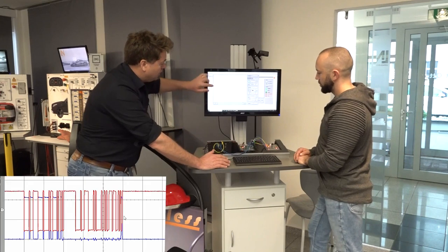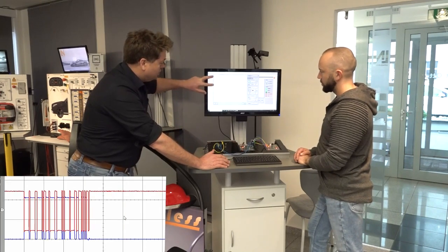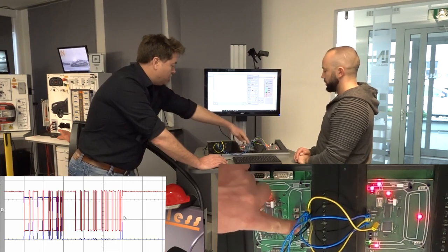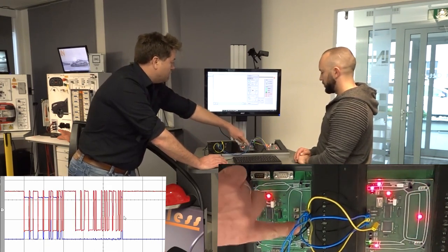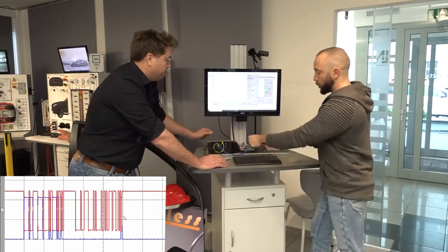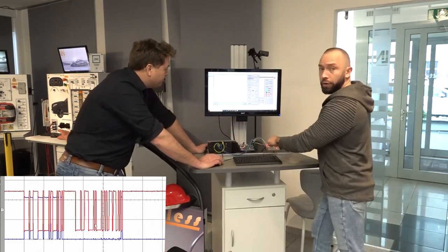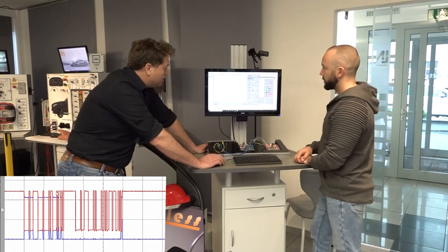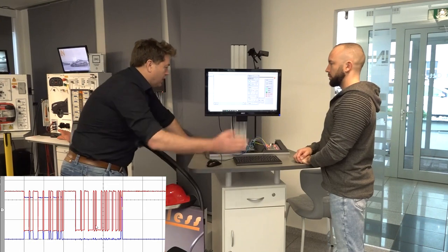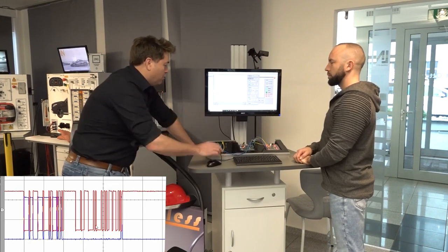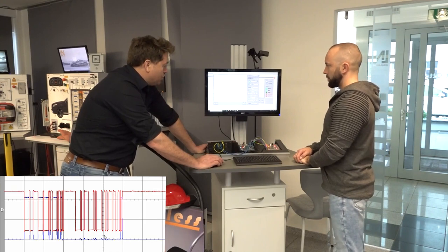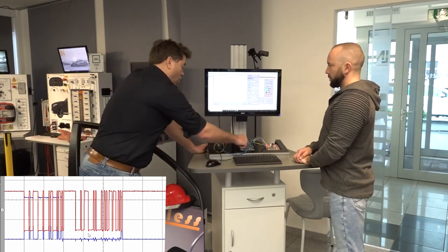We can tell it's low speed CAN because it has this 5 volt difference between them. And if we press the buttons here, we can see the system actually continues to operate on both sides, so not just on the front node, but also on the rear node. And you can see with the signal here that it's quite messed up a bit. So there's a little bit of signal getting around from the other side that we're picking up on the oscilloscope here. But the message of the system is working, and it's still operating.